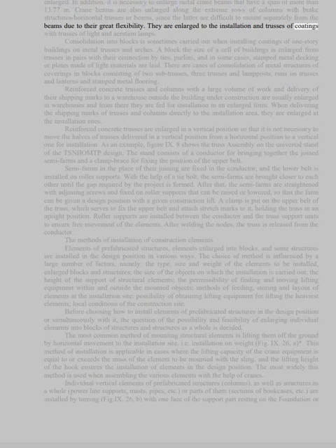From prefabricated metal structures, trusses with a span of 24 m or more and high columns are also most often enlarged. In addition, it is necessary to enlarge metal crane beams that have a span of more than 13.77 m. Crane beams are also enlarged along the extreme rows of columns with brake structures, horizontal trusses or beams, since the latter are difficult to mount separately from the beams due to their great flexibility. They are enlarged before installation, as are trusses of coatings with trusses of light and aeration lamps.